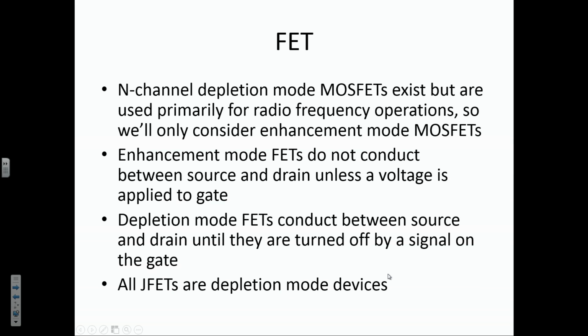N-channel depletion mode MOSFETs exist, but they're used primarily for radio frequency operations, something we won't deal with. We're only going to consider enhancement mode MOSFETs. Enhancement mode FETs do not conduct between source and drain unless a voltage is applied to the gate.